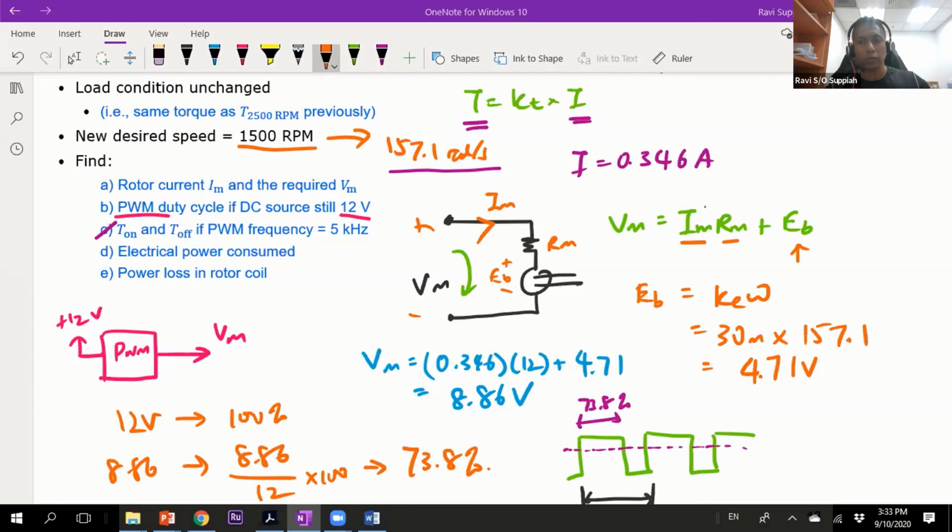depending on the motor you're using, you may or may not use a driver chip. If you're having those very, very small hobby motors, then you may directly drive it and it will still work. Anything a bit bigger, you will need some driver chip and an external power supply so that you have enough current to drive the motor.